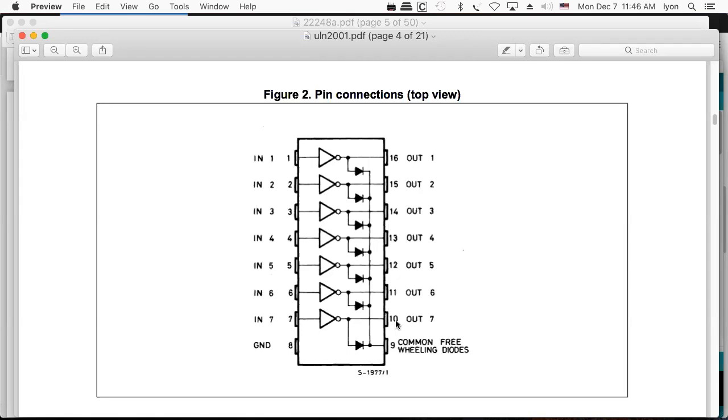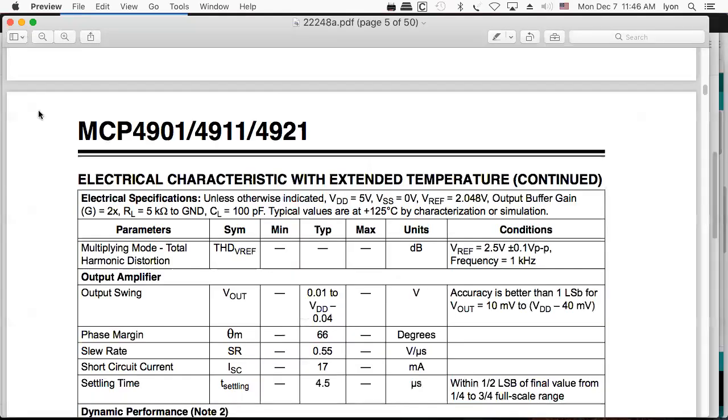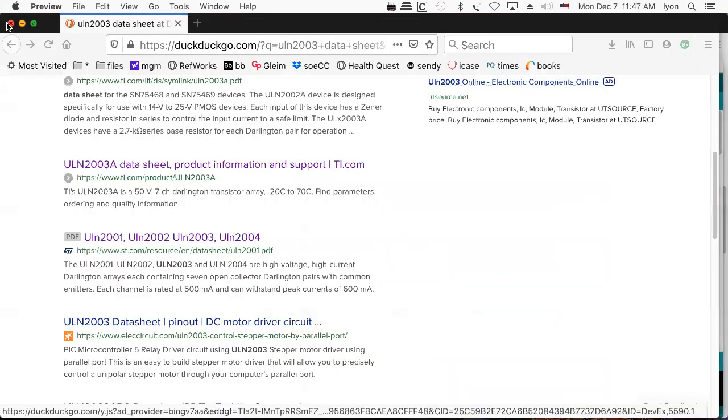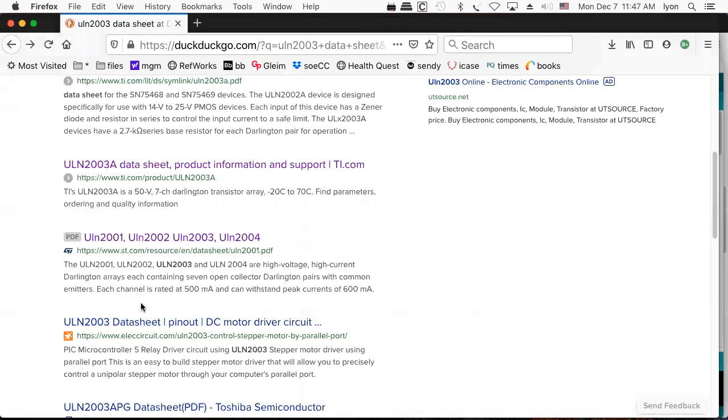If you're wanting to increase power to 2 amperes, I guess you could stack 4 of these things, but at some level you want to call it quits and just buy a different chip. And it's not meant for driving fast changing signals like the 4921. It's meant for going into and out of saturation like a switch. You're going to be wanting to operate these transistors in saturation mode. So it's very good for a stepper motor that needs substantial current.